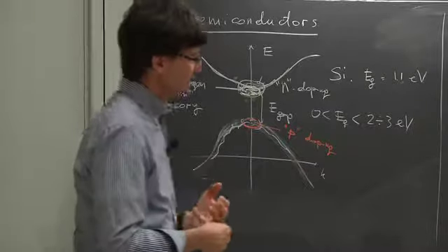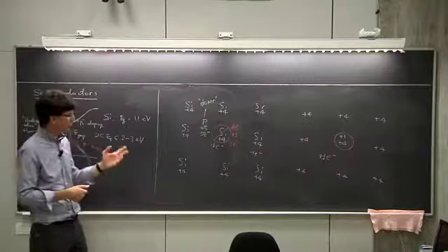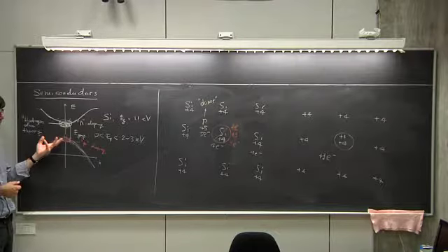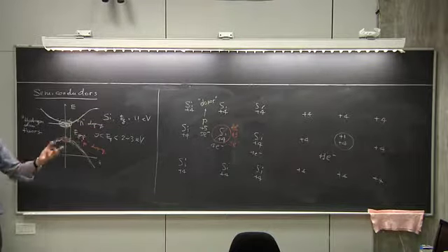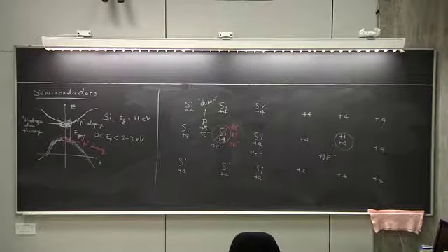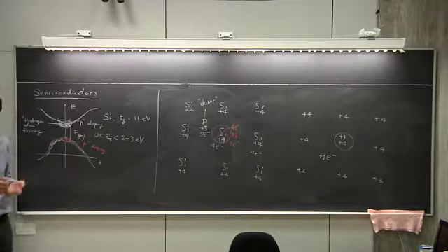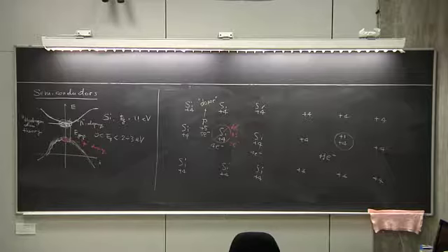But as long as you're below the solubility limit, the amount of carriers that you can generate with this kind of chemical doping is typically much higher than the one you induce with temperature. But the most important thing is that here you can really play with the concentration at your own will. You're not forced by temperature. You can have a circuit working at room temperature with an arbitrary conductivity because you just need to change the doping level. Of course, once you grow the crystal, it's done. The crystal has a given amount of doping. But you just buy another one with a different doping.